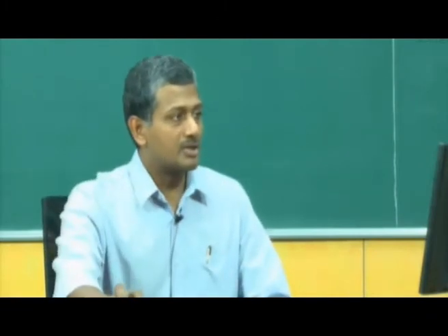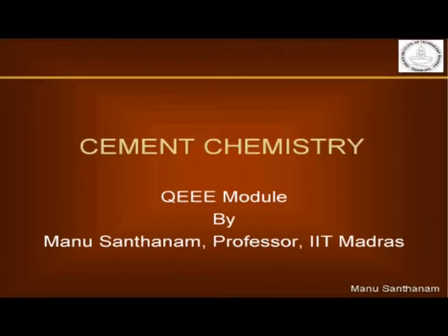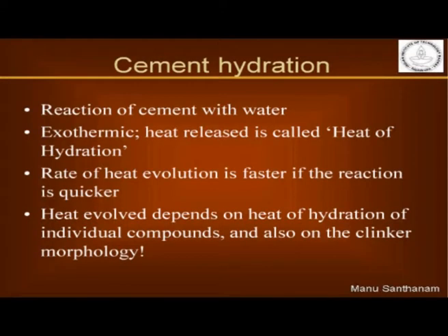Okay. So, today our emphasis is going to be on cement chemistry. First of all, what you need to understand about cement chemistry is the reaction of cement with water. As you all know, this reaction is called hydration, and this hydration reaction is also exothermic. That means it releases heat, and the heat that is released is also known as heat of hydration.